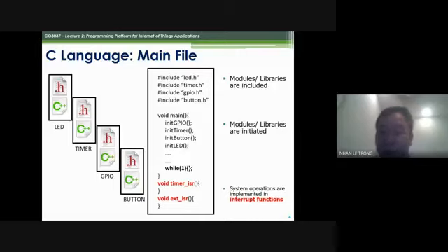It can be an external interrupt, it can be an ADC interrupt, a DMA interrupt, a lot of interrupts in the microcontroller platform. And yes, with a modern approach, right now you can implement a state machine in a while true, and from the timer, from the interrupt service routine, you set the state of your system. When you receive a signal, you set a state, and you process it in the while true.